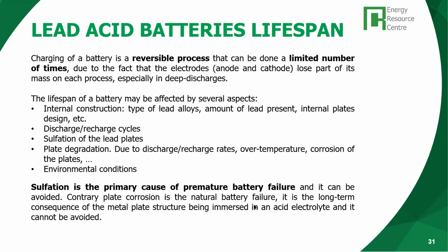Okay, so it seems like you are back. Good. Let's finish with the batteries. So basically, the primary cause of premature battery aging and eventually failure is the deposition of the sulfate ions in the lead plates.